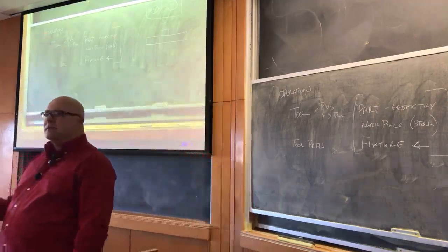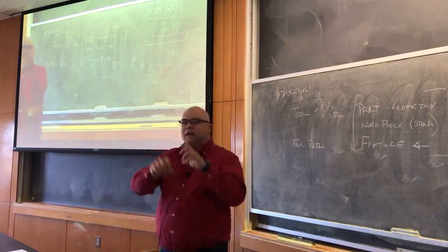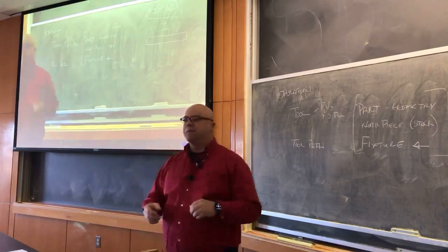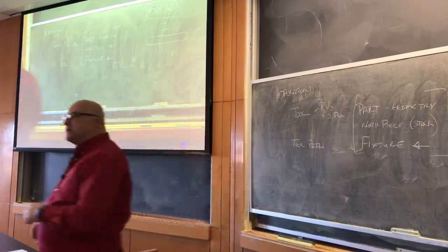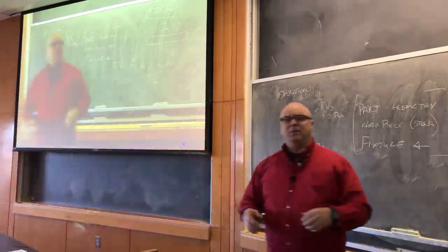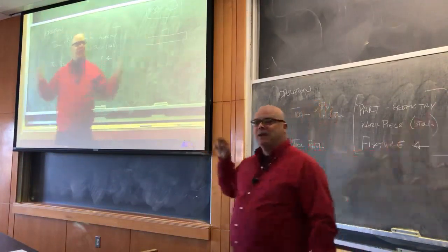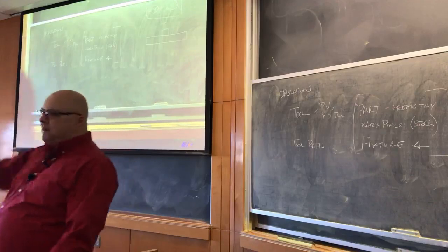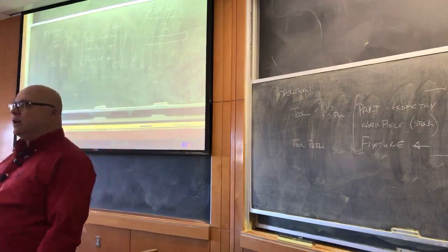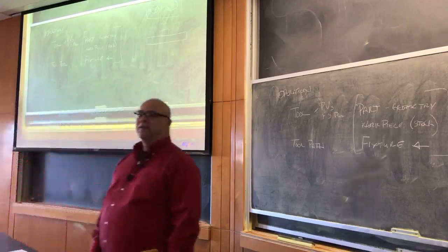The other one comes in and he's like, all right, how did that tool offset setting thing work again? And so he's fiddling around with setting tool offsets, and then he's like, oh crap, it's lunchtime. So he turns off the machine and goes to lunch. First guy comes back from lunch, thinks the thing that he's got all set up in the machine is still set up, because he set it up, he went to lunch, he came back. Machine looked the same. Cycle start. Spindle nose into vise. Spinning. Gearbox spindle gone. $10,000 first week.